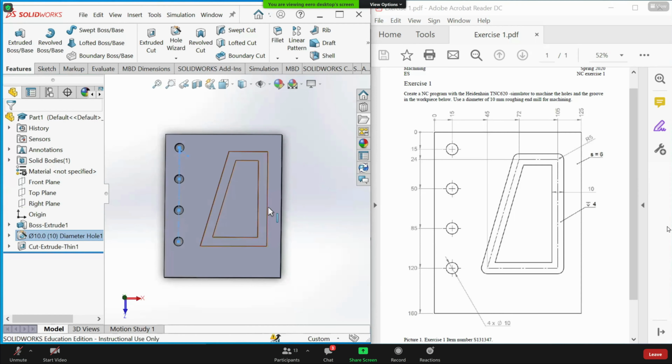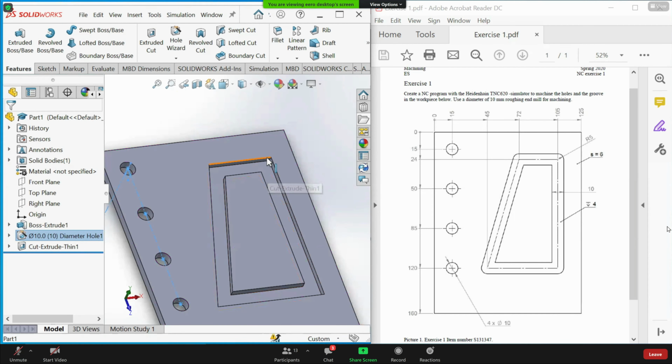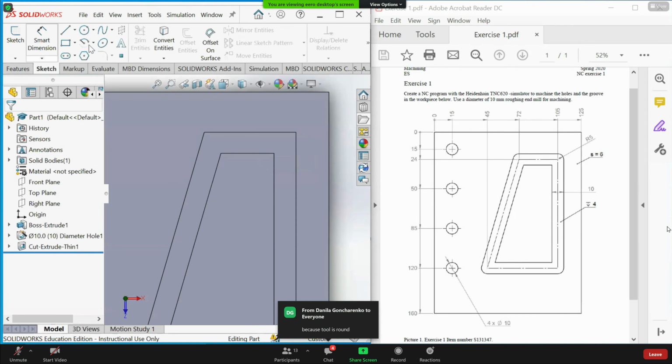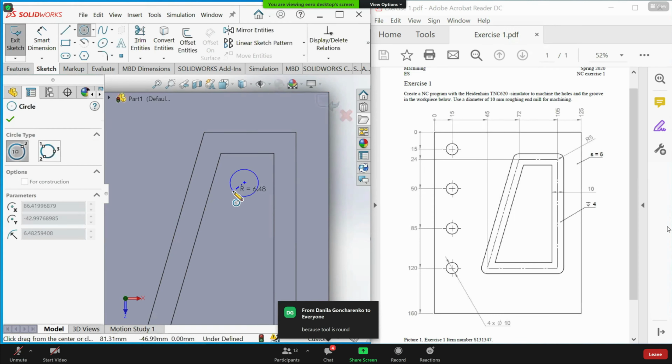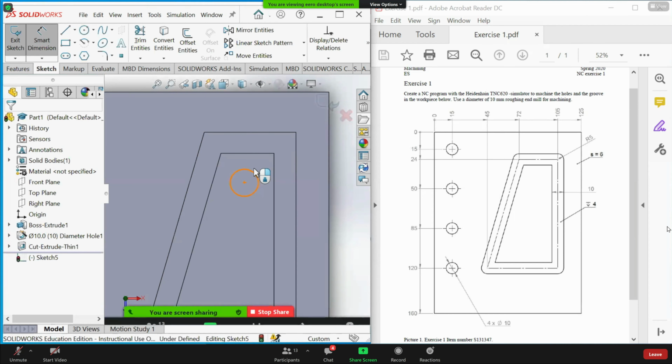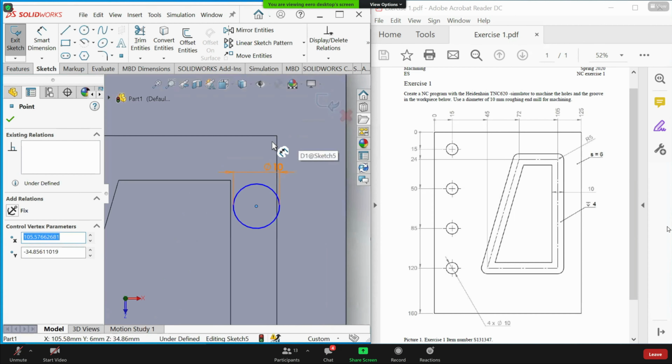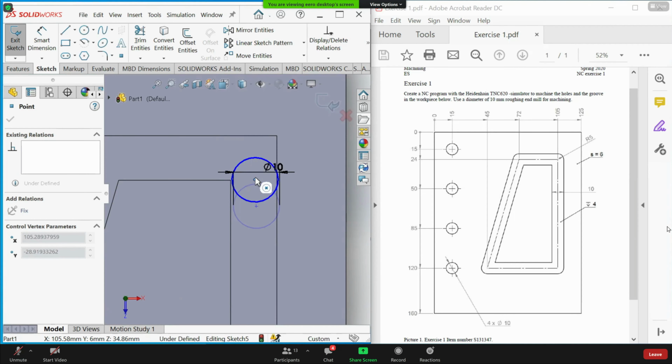Anyway, what is missing is the fillets from the machine shape. Why does this have to have a fillet? These outer corners. What's the reason for the fillets? Because the tool itself is round. Correct. Imagine that our milling tool with a diameter of 10 millimeters, once it's moving here on this groove, will leave a fillet there. A sharp inside corner in a groove like this is impossible to make with a milling cutter. Outside corners, sharp outside corners are not a problem. But inside corners usually are features that cannot be machined.